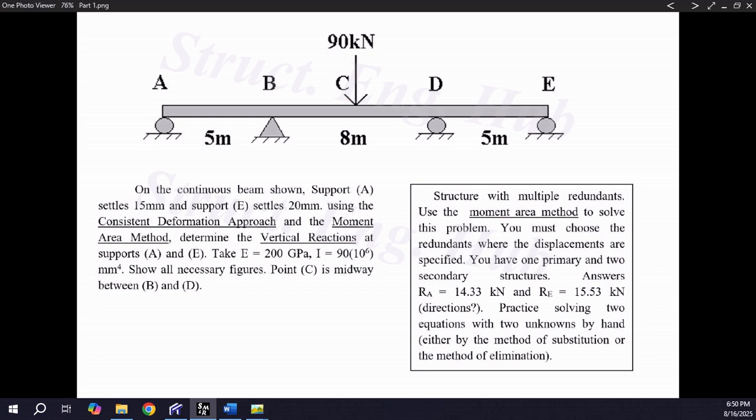We are given the modulus of elasticity and the moment of inertia of the beam, as these material and cross-sectional properties will be necessary during the solution of the indeterminate beam with specified support displacements. A quick look at the beam shows 5 reactions and 3 equations, rendering the beam statically indeterminate to the 2nd degree. The question requires us to find the reactions, but we will also draw the shear force and bending moment diagrams, as well as the deflected shape using the computer program.